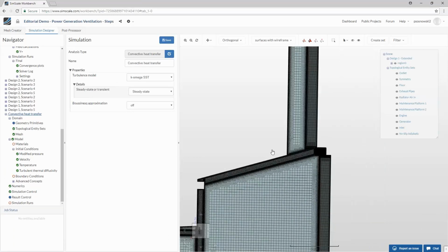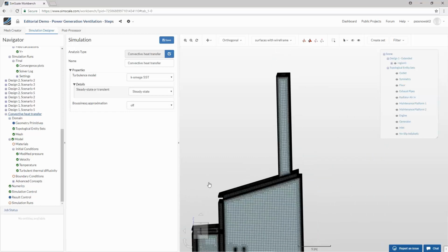What you want to make sure is, okay, let me grab a drawing tool. It should be available somewhere here. There we are. So the whole idea is that we are trying to prevent the flow to go back into the domain. Once you have an outlet, and let's say there is like a big recirculation vortex, it might be that some part of the air would try to go back into the flow area from the outlet. This is very undesirable. So you try to set it up as far as necessary to make sure that the air only goes out and it doesn't come back into the domain.